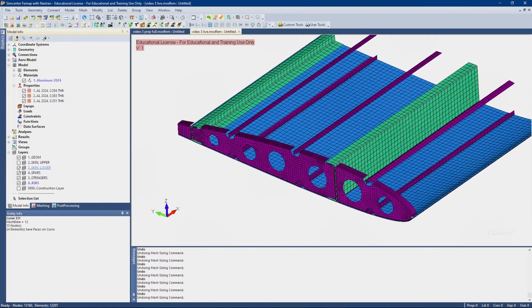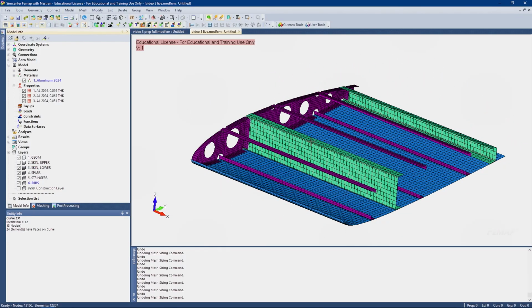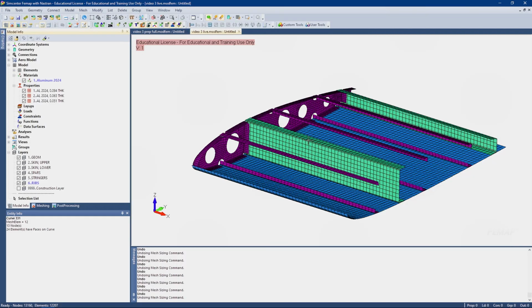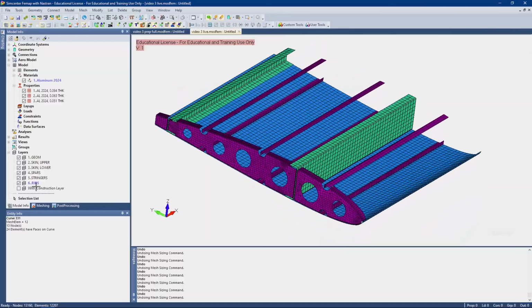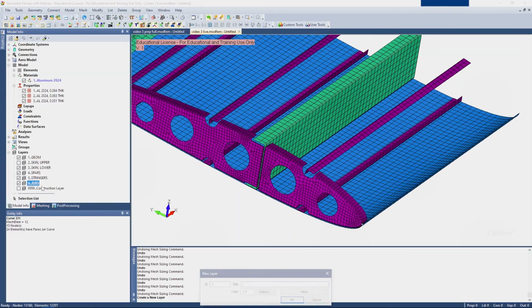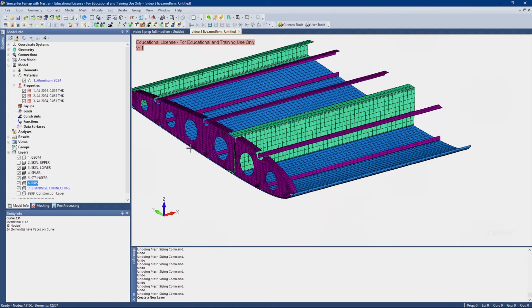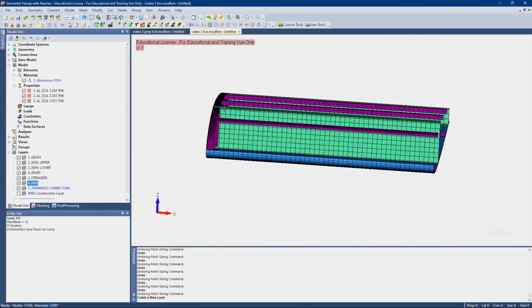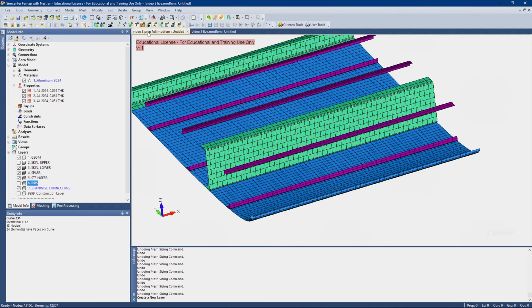You can now see we have our mesh all ready to go. So the next step is to, of course, start connecting everything together. So let's start with our easiest connectors. We'll make a new layer, call this span-wise connectors. Span-wise meaning along the span of the wing. So, in this view from left to right, that's span-wise. Let's turn off our ribs for now.